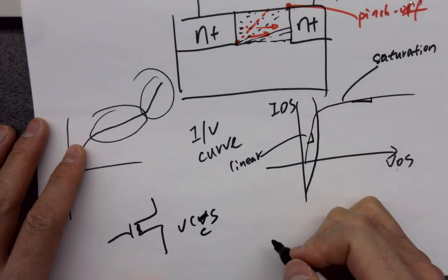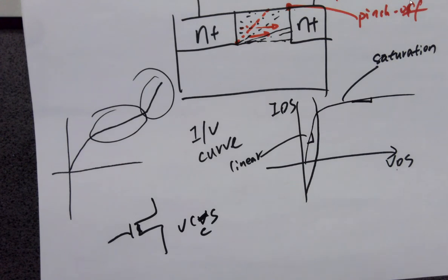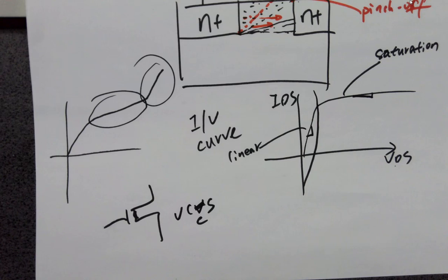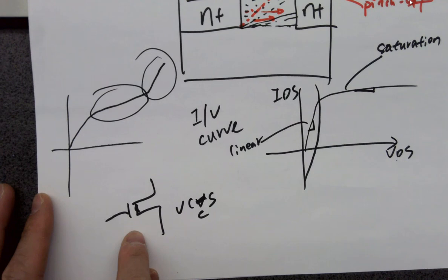That's why, in your Thevenin's equivalent circuit, whenever we are dealing with current sources, we disconnect them. Why? Because they have a super high internal resistance. So in order to become a current source, first the current shouldn't change. It's a source, right? If it changes, it's not a source anymore. Second, it needs a really high internal resistance.